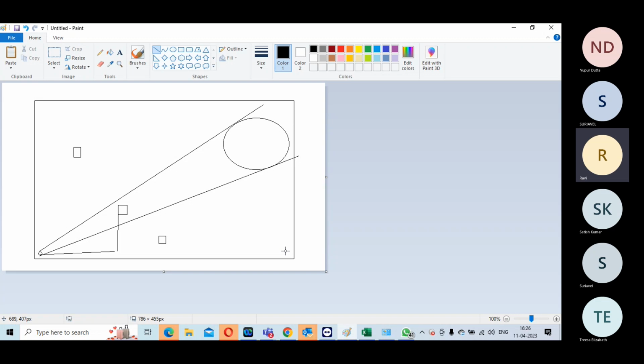Post CTS setup, the first thing you should do is not use data path optimization at that time. So in post CTS setup, enable clock skew optimization first, for it to actually do something. Run CCD if required, if the violation is large, and let it optimize. Then you can work on the data path optimization.